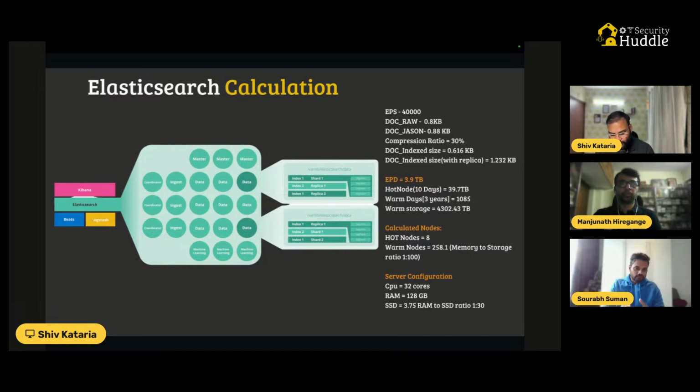It could be from the application whitelisting installed on your system, from the endpoint protection solutions installed on each of the computers, from an agent sitting on the system and fetching all those logs, a file reading system, Filebeat, or any type of solution sitting on your computer. In the European region now, customers are even implementing EDR on their ICS systems, so their maturity is very high. They are implementing endpoint detection and response systems on each HMI with support from the OEMs as well. So it depends on how rich your telemetry data is from the endpoints and from the network devices.